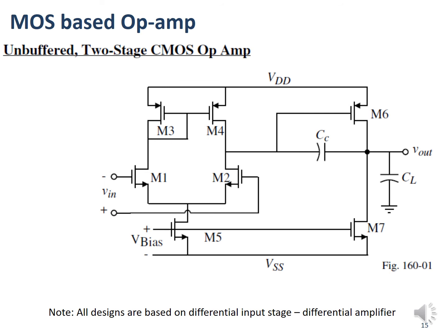So this is an op-amp based on a MOSFET type transistor, and again it's more or less exactly the same concept here. I've got two inputs, the negative and the positive. They both go into the gate of these 2 transistors, and that controls the currents in those 2 lines of circuitry that go up through M3 and M4.